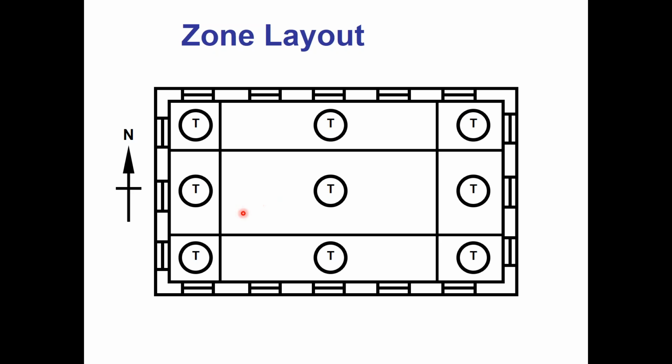Now, I may compromise and combine some things. Like this guy up here in the northeast corner, I may choose to combine him with the north. Yeah, he's going to get some sun in the morning. Maybe I'm not super concerned about it. Maybe I can just deal with that for an hour or 2 before the sun moves around. Not a big deal. And maybe I had the same feeling about this guy over here. I could start combining zones to save cost if I wanted to: 1 less VAV controller, 1 less thermostat, that kind of idea.